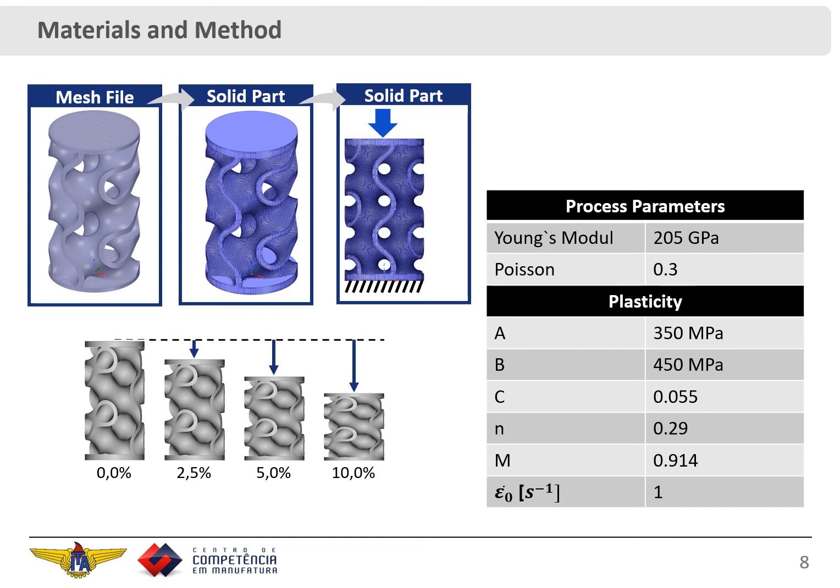So I chose the Johnson-Cook plasticity model because it's the most used for manufacturing process and manufacturing analysis due to the good plasticity representation. I have here some properties of these materials. I have to say now that these were properties found in the literature. It was not made a proper measurement of this material.